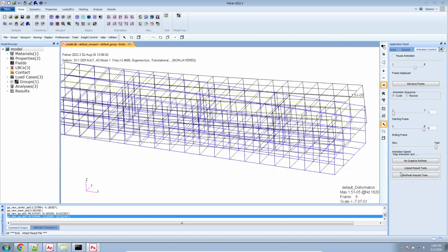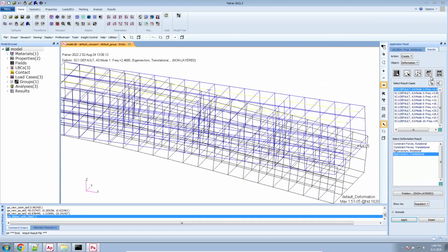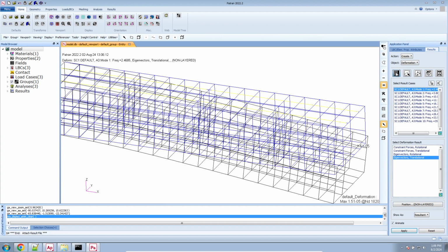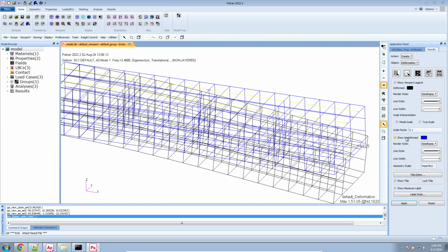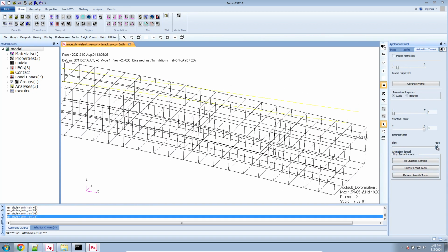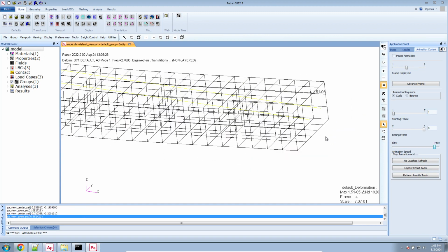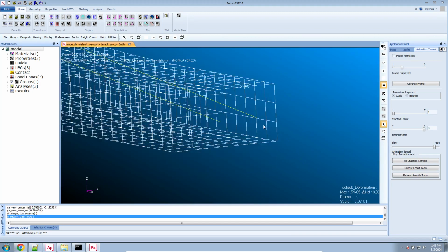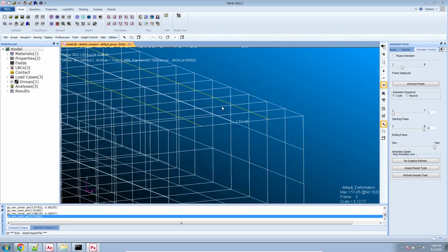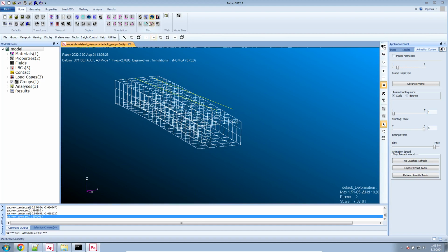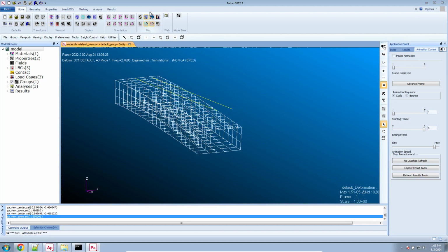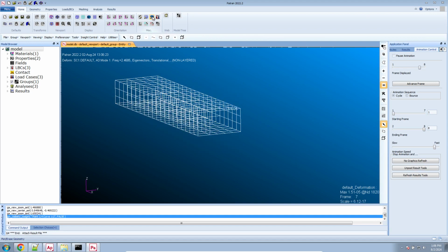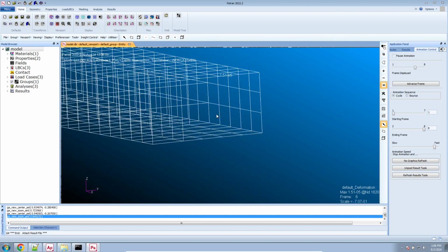If you look at the beams, and let me undo this. Let me hide. Here I'm going to select on tab 1, tab 2, and tab 3. Let me deselect the checkbox for show and deform and click apply again. And let me slow this down. And here you can see that in yellow, that's the geometry. That's the geometric curve. What you can do here in the home tab under the miscellaneous group, click on the green button. The green button is going to hide all the geometry. So now the yellow curves are hidden.